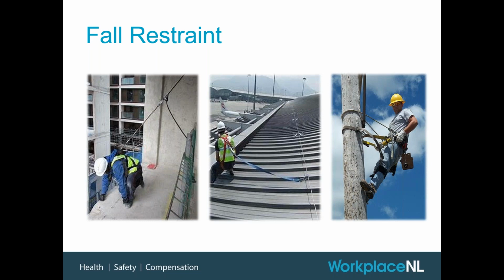The middle one there is a flat roof, or it looks like it's got a bit of a pitch to it. And basically what they've done is they've installed this horizontal line that runs along that 6 foot edge where you would have to tie off. So you can be in the safe area. Outside that 6 foot edge, you can clip on, and then you can step over into the area that you need to access.